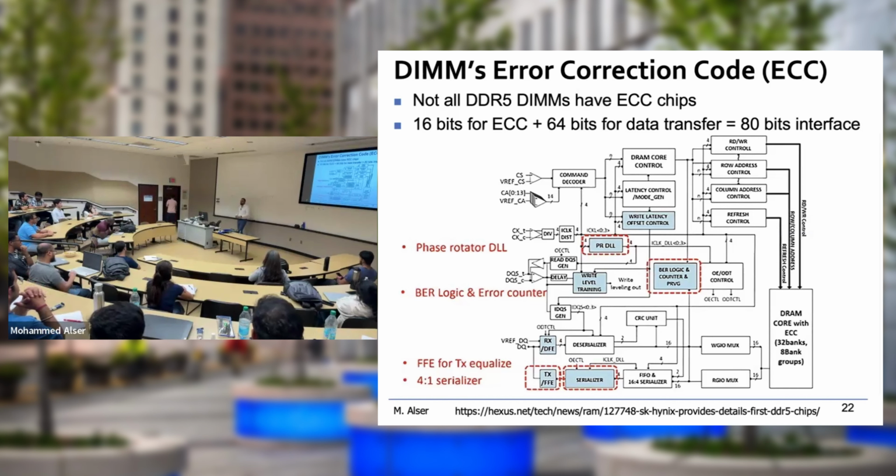So Rowhammer is basically when you activate one row in the DRAM and you activate another row that is nearby the first row, and you do that very quickly. Let's assume it's row number 1, and you activate row number 3. It's not right next to it, but nearby, okay? Now keep activating this, activating that, activating this, activating that. What will happen? This is going to impact the data stored in row number 2. It's going to really alter the bits stored there.